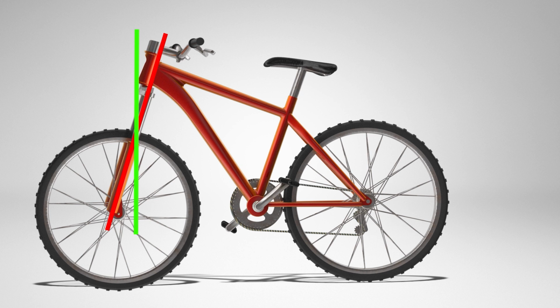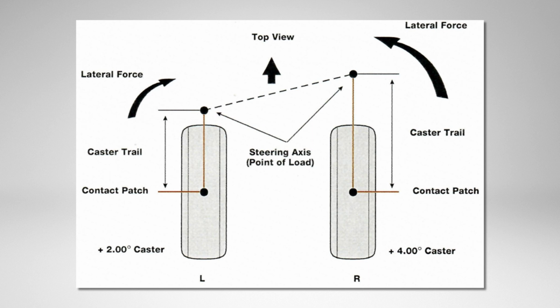In other words, the weight or load is pushing the wheel forward instead of the load pulling the wheel. Two significant drawbacks to large caster trails are increased steering effort and increased road shock. Caster's influence on directional control is significant, providing both steering returnability and directional stability. A difference in caster between the left and right side of the vehicle will induce a pulling condition.